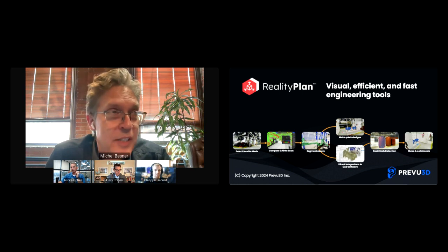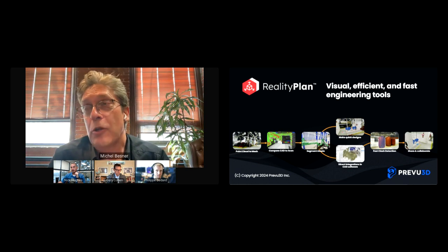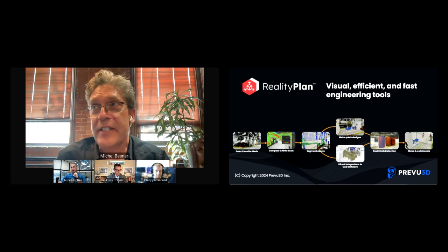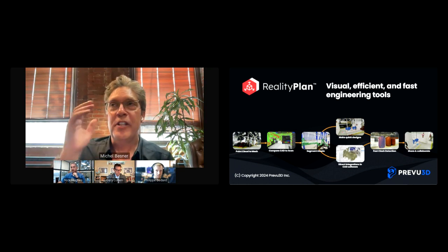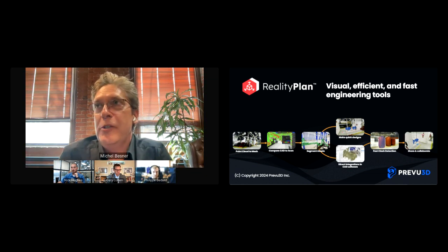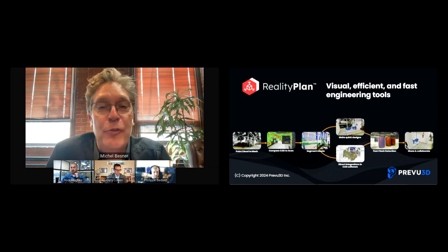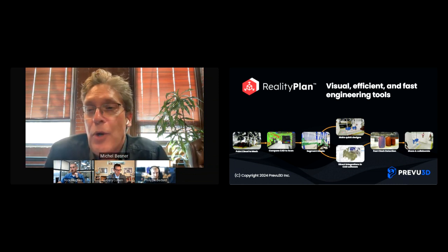But even more, sometimes you have to back model assets that are not necessarily needed for your design project as such, but you need their context, you need a visual reference. Let's say you're changing a specific configuration of a machine, and you still need the equipment around it as visual context. If you only have a point cloud, you need to model those assets just for referencing. So leveraging these meshed assets that we generate out of our product directly into the Revit families is also